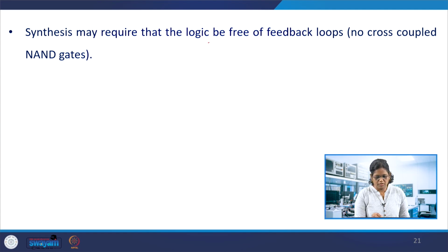So, what is that level sensitive behavior? It is feedback free. If we have NAND gates, the 2 NAND gates should not have any feedback. That is, one output should not be connecting to the input of another, and the other output should not be connecting back either. A cross coupled structure should not be there in the synthesis process for combinational logic synthesis.